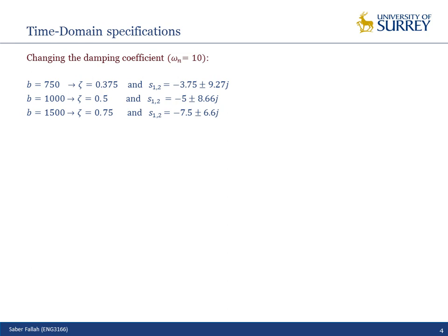Here we have the largest zeta omega n. It means the system will settle down much quicker than the 2 others. We have the highest damping ratio again for the third one, more than the 2 other cases. It means we have less overshoot compared to other cases. Correct? So we have some idea how the response will be.